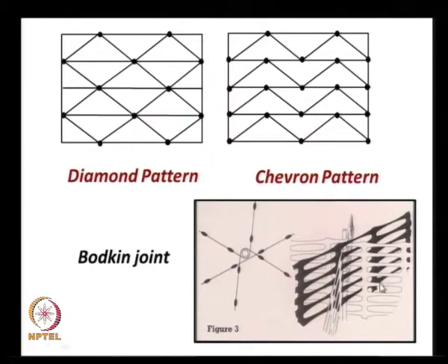Like this, we have a plastic rod, and we have the geogrids going in different directions, in the length direction and then the transverse direction, and we attach them by passing the geogrid through each other through these aperture openings, and then we insert this plastic rod in between to form the joint. These dots are all the joints.